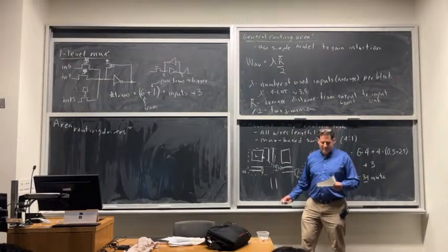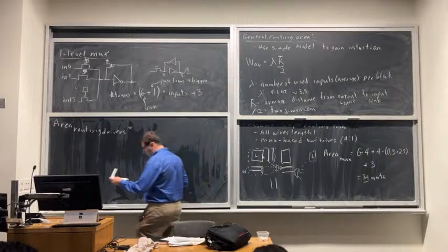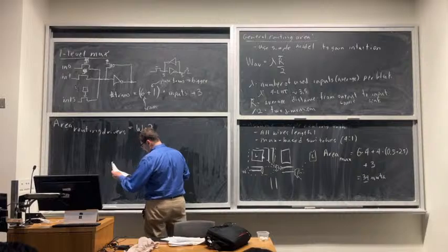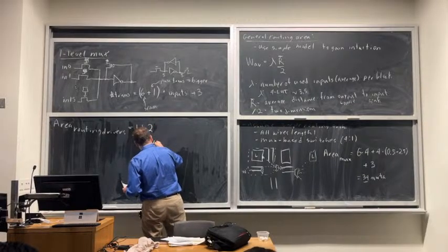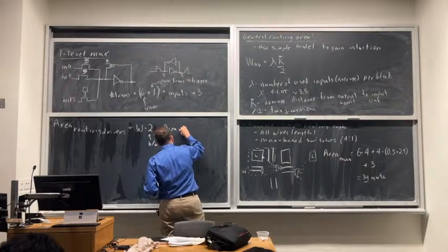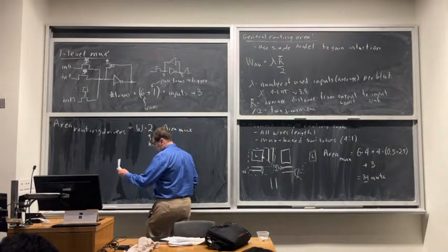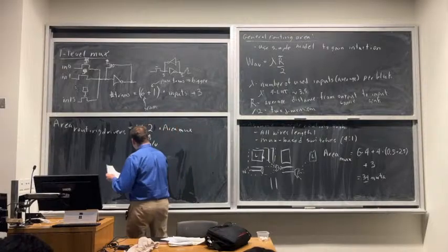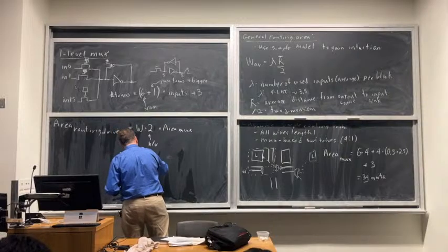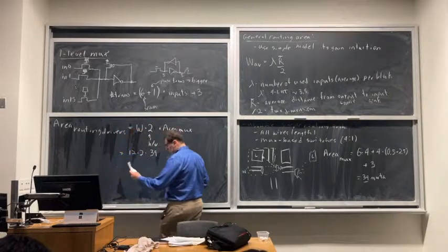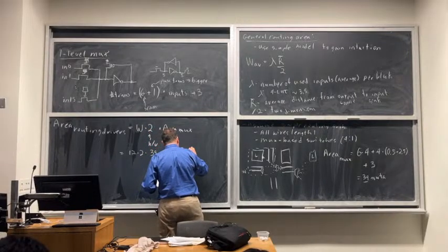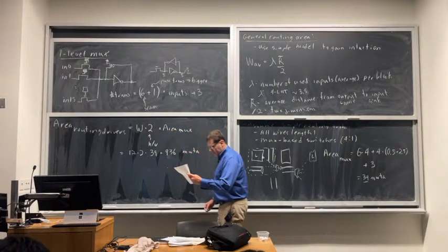2W? Yeah, so we just have 2 W's. So W in the horizontal direction, W in the vertical direction, okay? So that 2 comes from horizontal or vertical. And then we just need to multiply by the area of the mux. If I plug those numbers in, we worked out that W is 12, and the area of this is 39 of these minimum width transistors, which means the area of this is 936 of these minimum width transistor areas.